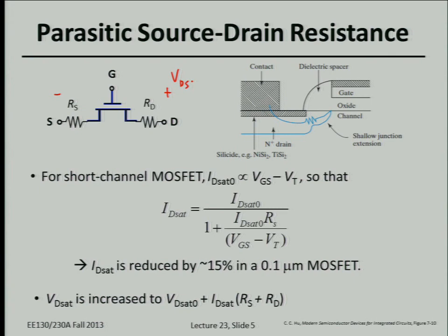Okay, so in an integrated circuit, what you can do is apply a drain to source voltage at the terminals, the tungsten contacts. And in response, if the gate is biased above the threshold voltage, then you can get current to flow. Okay, so this is ID sat.